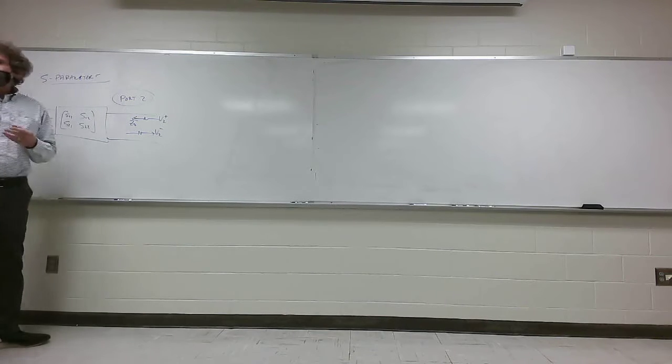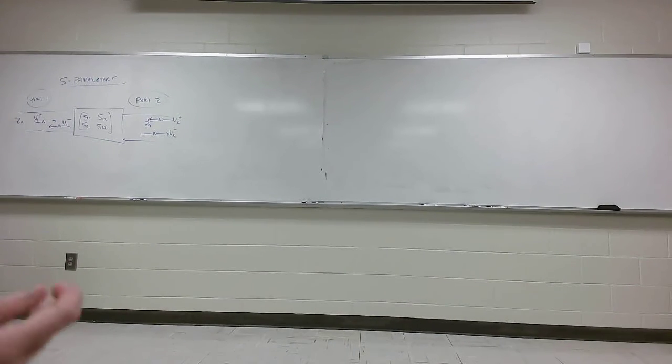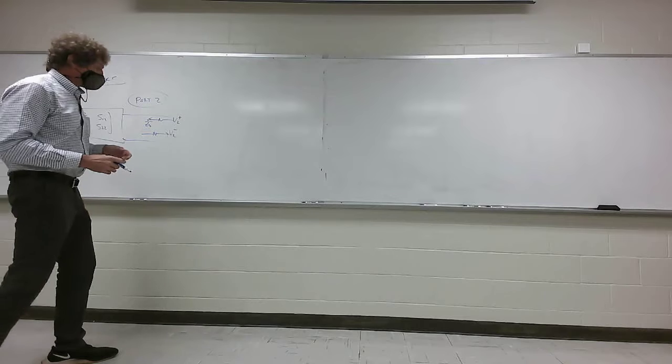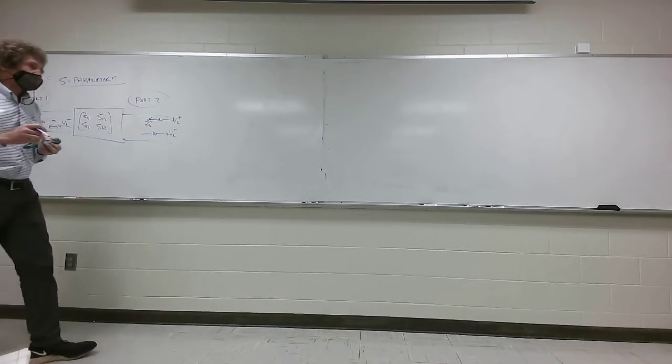Now you'll notice there's no electric fields indicated. These are voltages measured from the two conductors, like the inner conductor of a coax to the outer, and they vary versus distance down the actual cabling. So the relationship between these parameters is given by the S parameters. A lot of times you'll just see a solid block S there, a big black S. That means it's a matrix.